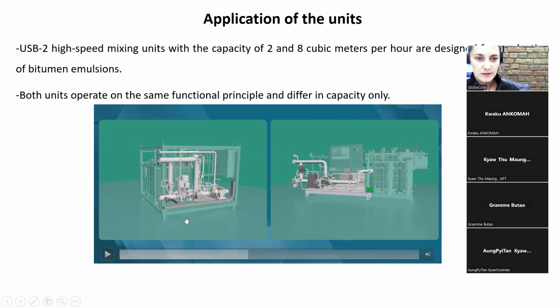And we have 3 sets or 3 points where the sensors and detectors are installed. So we measure pressure and temperature before the bitumen pump, before the hydrodynamic mixer, and before the colloid mill. So that's to protect our machines from any alarm situations. And all the pipes we have covered in a heating jacket to avoid sticking the product inside.